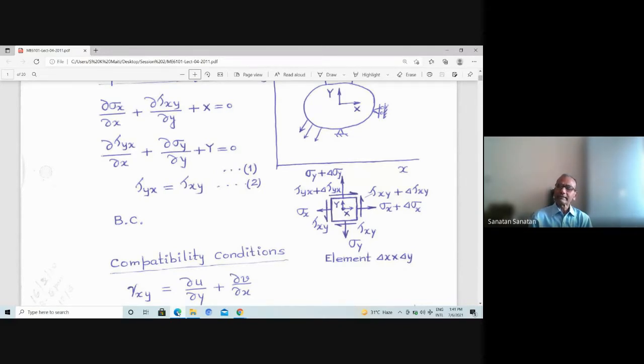Have you come across problems of statical indeterminacy? Have you? You have actually had problems of statical indeterminacy in statics. You had, because if you try to say that it is a simply supported beam with two supports at its end, then you have two support reactions as unknowns. It's a simply supported beam, horizontally oriented, with support in the vertical directions. There, two reactions are there. Sum of the two reactions is equal to external load. That is the statical equilibrium equation.